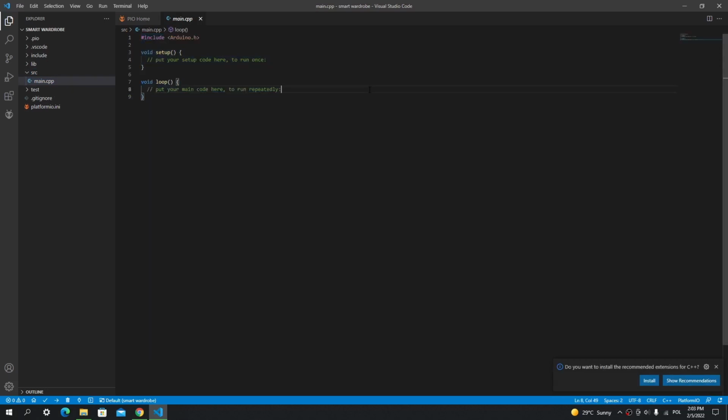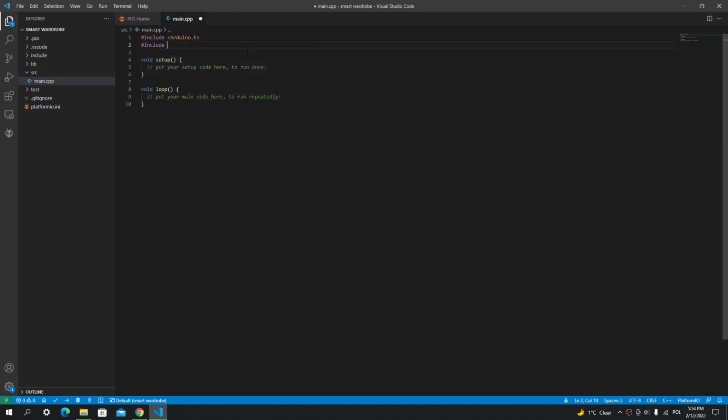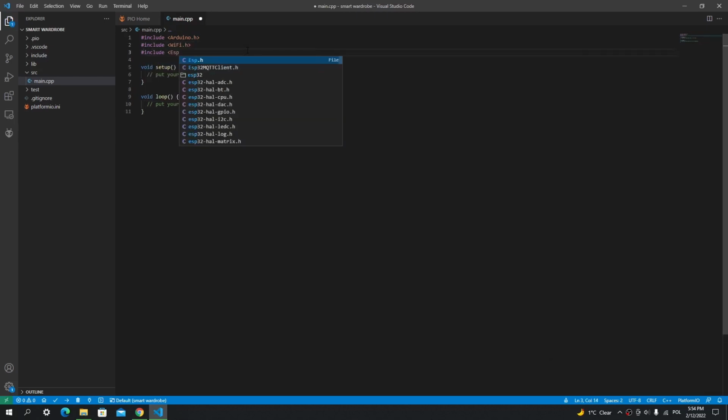At the beginning, I will use the ArduinoOTA library. It allows to program ESP wirelessly using Wi-Fi. You don't need to connect your computer with a cable. It's useful if the ESP is in a hard to reach place. Let's add some imports for that.